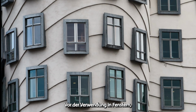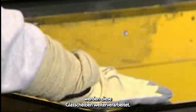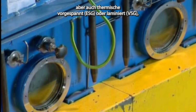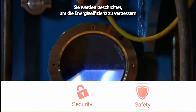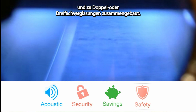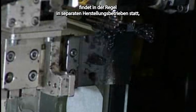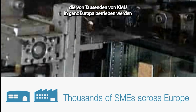Before being used in windows, windscreens or any other application, these pieces of glass will be further processed. Depending on final usage, they will be cut but also tempered or laminated to give them safety characteristics. Coatings will be applied to them to enhance their energy performance, and they will be assembled into double or triple glazed units. These processing activities usually take place on separate manufacturing sites operated by thousands of SMEs all across Europe.